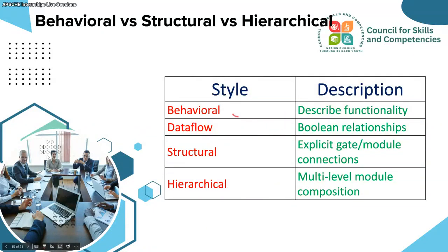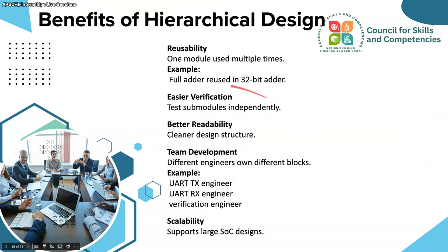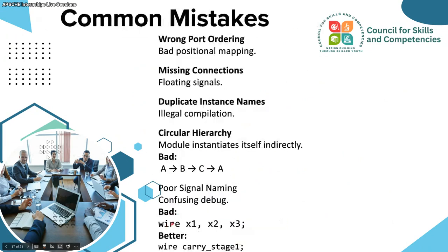In the behavioral model, it describes the functionality. Dataflow describes the Boolean relationship. Structural explicitly uses gate module connections, and hierarchical is multi-level module composition. The benefits of this hierarchical module are that we can reuse it, easier verification, better readability, and team development. Examples are TX, RX, and then verification engineering, and it supports large SoC designs.